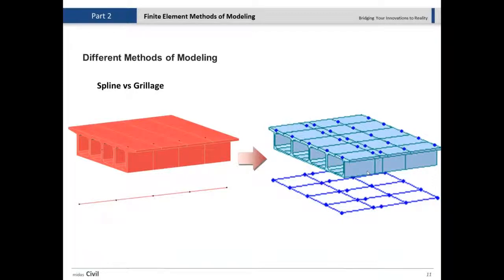Especially when we come to the curved geometry, maybe for straight we don't feel that much of a difference, because it's kind of symmetric. Every load kind of goes vertically, so we don't feel it that much. But when it comes to curved geometry or irregular shapes, that is the time we see the effect of these transverse elements in guaranteeing the lateral stiffness more and more.